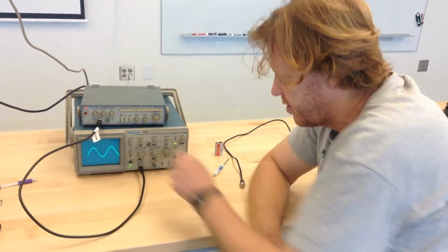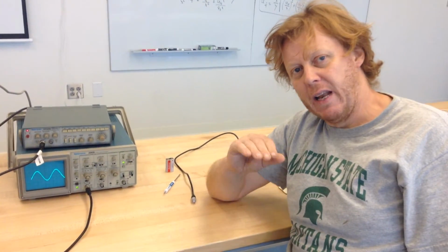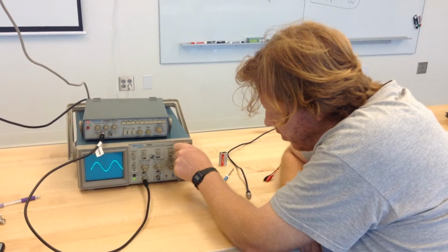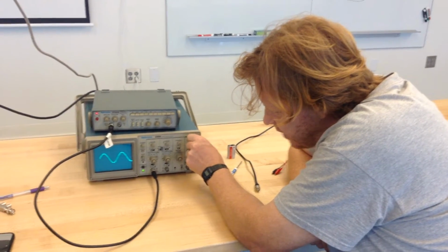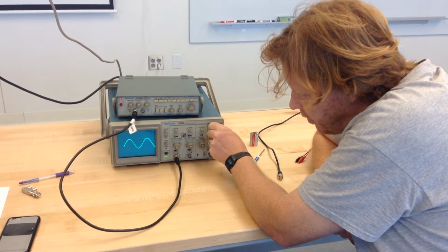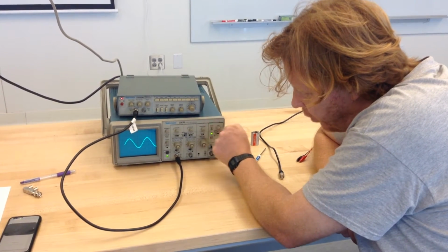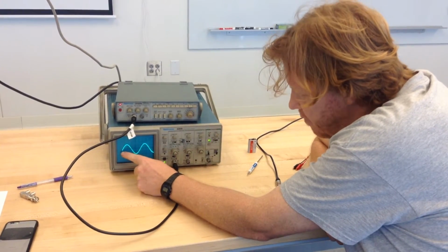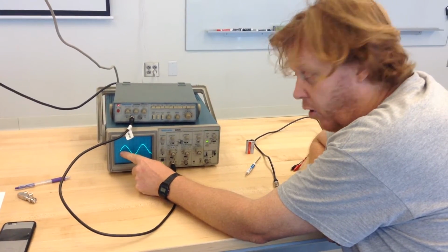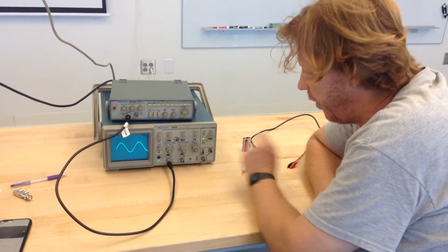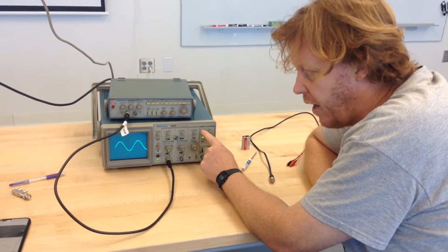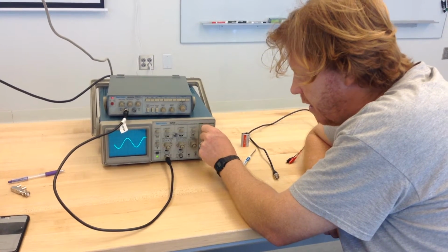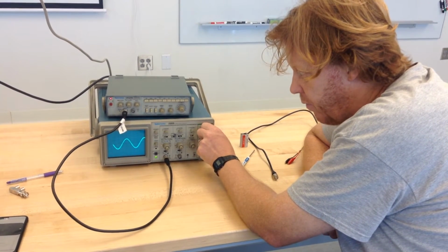We want to talk about when the signal starts. That's called the trigger level, the level at which I'm going to start drawing the picture. This says level. Now look here, as I turn this knob, it starts at a higher or lower voltage. Supposing I wanted to start, say, at 0 volts, I'll put it there at 0. I'll explain how I know this is 0 later on. Now, every time the signal is 0 volts and increasing, then that's when I'll do it. This is a slope knob. I can say trigger on a decreasing voltage. Every time you pass the same value and you're decreasing, then trigger.